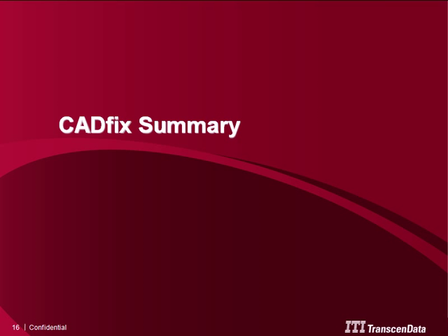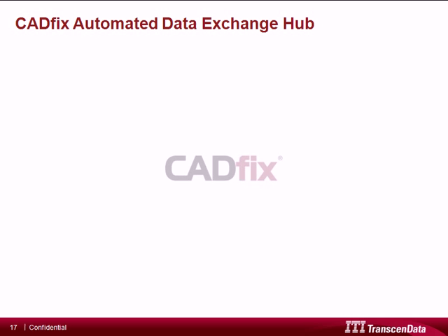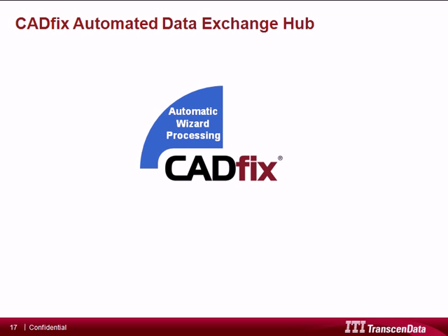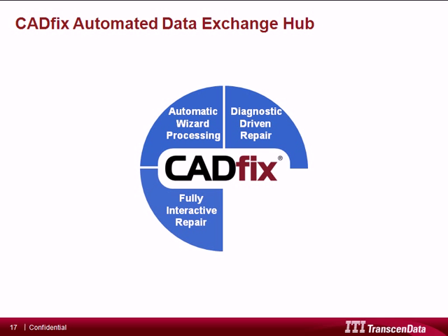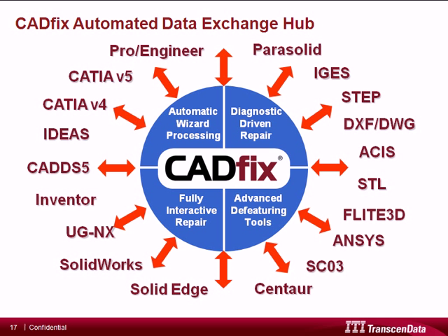In summary, CADfix is a tool which helps to simplify and solve your CAD data exchange problems. It gives the user automatic model translation and repair, all controlled with the CADfix wizard. The wizard process is supported with the intelligent diagnostic system, which guides the user to solve more significant problems. The user can also choose to process the model in a fully interactive way and has access to a wide variety of tools and checks. Finally, with the appropriate license, CADfix also allows the user to simplify models for CAE and manufacturing.